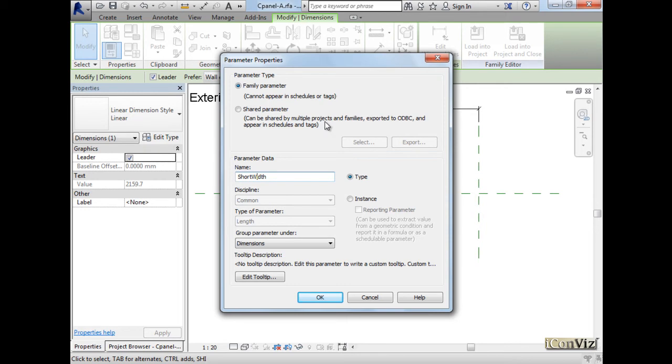And whenever the name of the parameter is 2 words or 3 words, I always keep them connected, no gaps. Sometimes some parameters are used in other parameters. For example, we could say length equals width by 2. It can be done by formula. We'll do that here. So parameter names, always keep them short, simple, no gaps, no percentage, no at symbols, no string symbols. Okay.